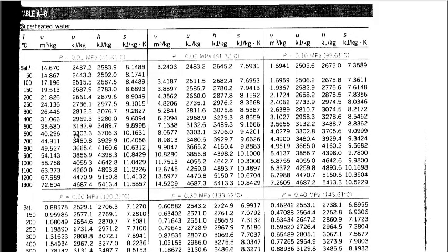Okay. Now there's a few other interesting features to point out in this table. The first is that you'll notice that the top of every single temperature column is listed SAT. Okay. So the data that's listed for the SAT line, what that SAT stands for is saturated vapor. So these are the data for saturated vapor water, okay, at the various pressure subtables. And you'll also notice that in parentheses next to the pressure listing, there's a temperature that's listed. That's the saturation temperature of water at that pressure, okay?